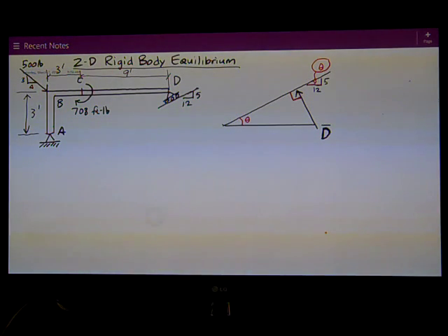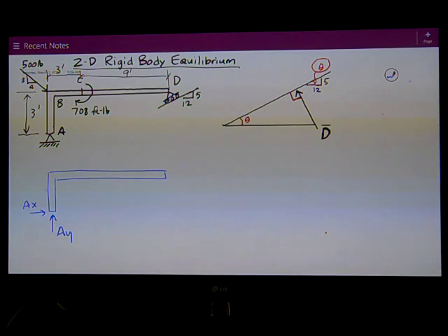And so, of course, the first step on any of these problems is to draw a free body diagram. Draw the L-shaped bar. At A, it's easy. I just have AY and AX. Everybody knows that. I have 3 feet to this 500-pound force at a 3-4-5, so it's more horizontal than it is vertical. So it's 500 pounds. I draw that on there, 3-4-5.